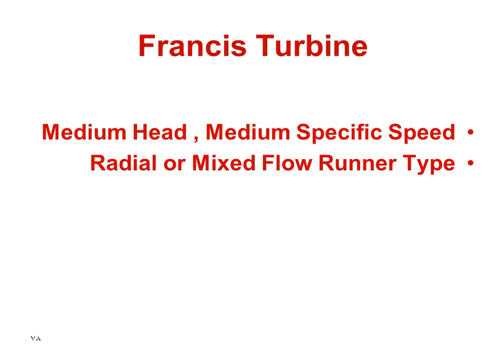This lecture includes details about Francis turbine. Francis turbine is always used under medium head application, and it has medium specific speed. It can be radial or mixed flow runner.